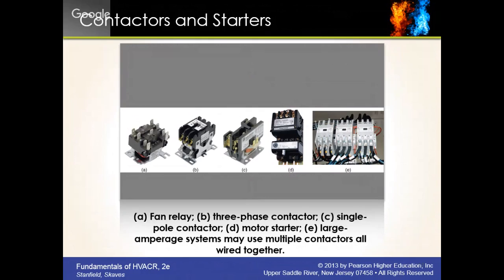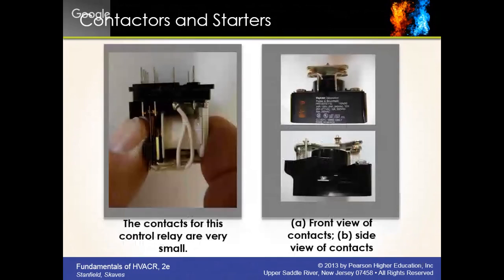Relays and contactors and starters all have contacts that open and close to complete or disconnect a circuit. Ice cube relay on the side there. Contacts for control relays are often small. This is because they do not need to be connected to the load current, since they are only relaying the signal. Repeating myself, typically relay contacts are rated for 15 amps or less.